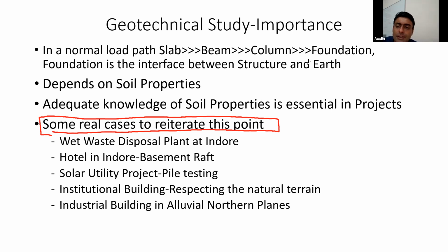Yes, there are a few questions I'll just take up. Mr. Vikram is asking, can we provide a filter media all around the basement to stop the capillary action of groundwater? But see, then those filters have to be really very, very fine, isn't it? Because water needs just a very small space to pass through, so I don't know how effective that filter media would be.